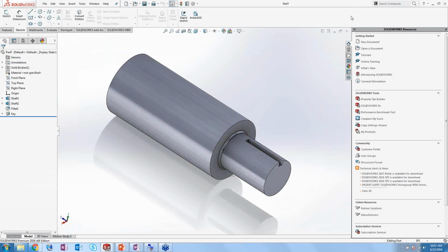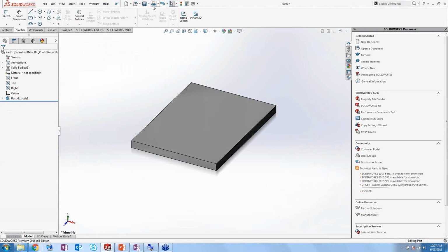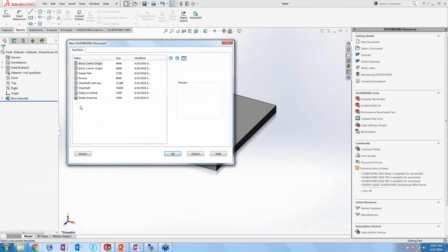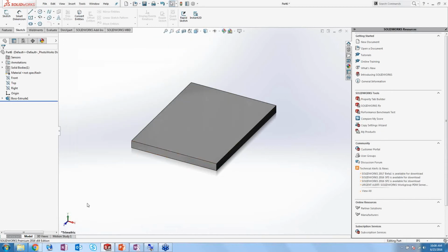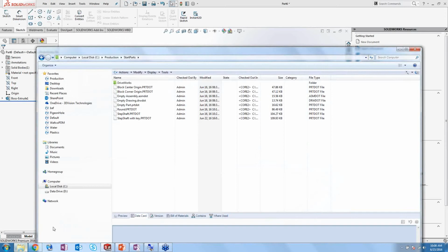And actually, SOLIDWORKS makes things a little bit easier for that, too. So right now, this list isn't too bad, but certainly you can imagine there's no reason not to make a bunch of start parts. Have all your primitives in there as you're going through. These are simple ones, but you can get very complex and build these all up. So over time, you might get actually too many of them in there to list. So SOLIDWORKS does give you the ability to actually organize those.